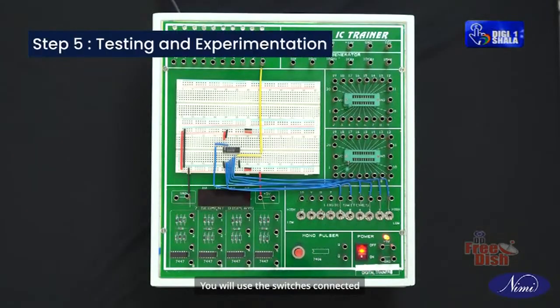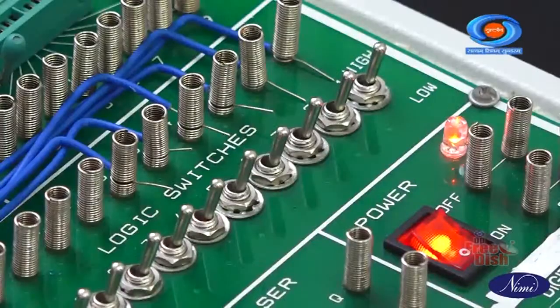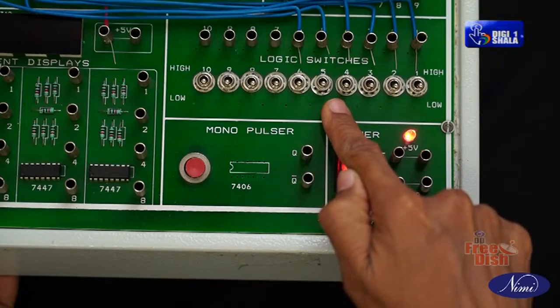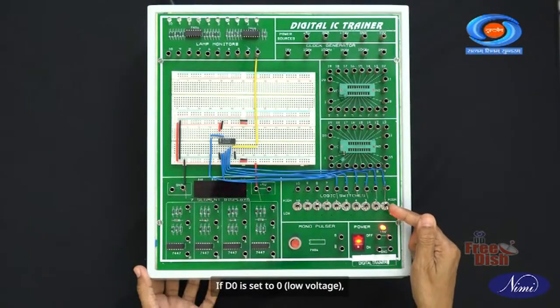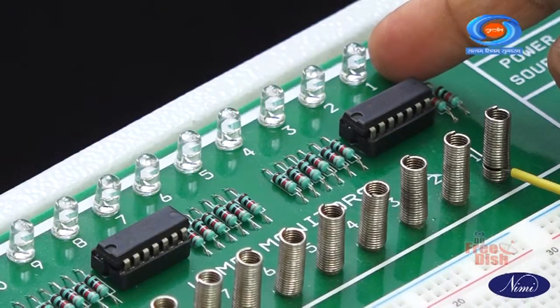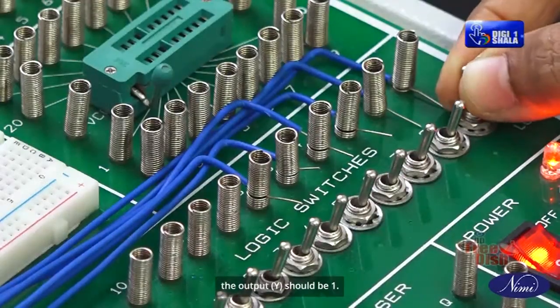You will use the switches connected to the data input pins S4 to S1 and the selection input pins S5, S6 for the first multiplexer and to test various combinations. Toggle the switches S6 and S5 to 0-0 combination. Output will be data input 0. If D0 is set to 0, the output Y should also be 0. If D0 is set to 1, the output Y should be 1.